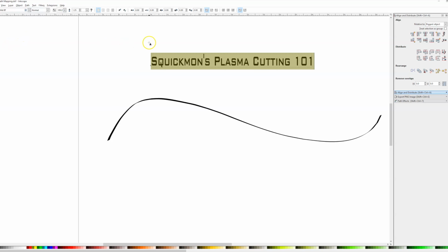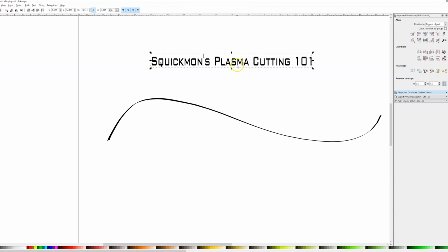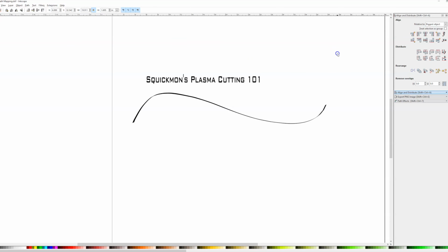Once that's done, cursor. So now we have this text. Move it around. We are going to highlight over both of these by clicking and dragging to select both. Just to explain this, I always have my finger on the escape key. So anytime it's not doing what you want, if you're trying to follow along with these videos and it's doing something funky, just click the escape key at least two to three times. Three times will get you out of everything, and then you can select the pen or the text key. So just know that I always have my left finger on the escape button, so that'll help you out a lot when you're first learning.